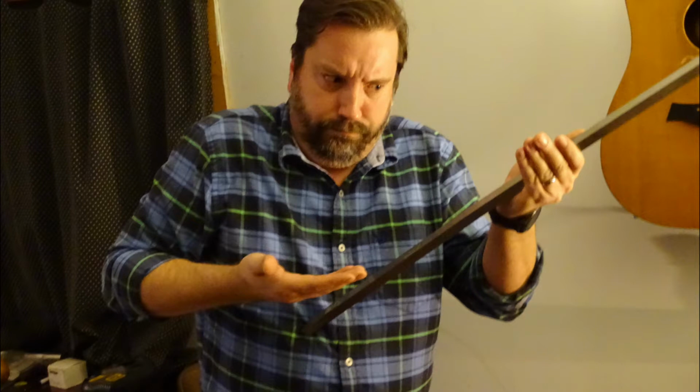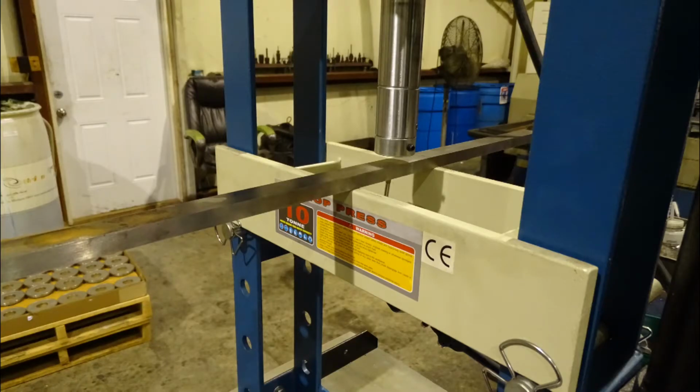Our team concluded that this may be due to the fact that the equation is calculating a fine point where the force is applied to the beam. In our experiment, this wasn't the case, as the force applying apparatus was approximately 1 inch in diameter, so this would apply the force to a larger surface area, skewing our results.